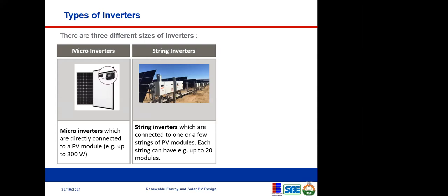Sorry, sir. Sorry to draw you back. Please, I'm not getting you. This string inverter you're talking about, is it that you say 10 modules to a different inverter, or the 10 modules to the same inverter? Yes. 10 modules to one inverter, another 10 modules to one inverter. So how do you conduct them through the charge controller? And how do you bring them together into one inverter? So there's a combiner box that does that. That's the combiner box that someone was asking about the other time.